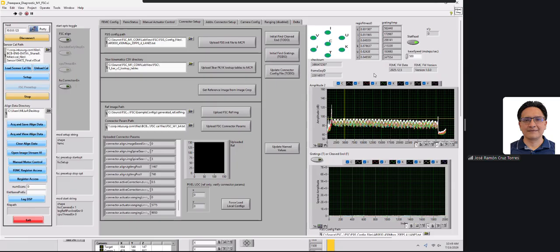And it's a continuous spectrum, right? There's no hard cutoff or anything like that, it's just indicative of generally where we are. What I'm saying is not coded into the logic, it's just a general rule of thumb for me. Anywhere under 0.3, like 0.1 or 0.2, either means you're not coupled at all, or you're coupled onto the wrong pole, because that has to match exactly the mapping that you have in the sensor cal file.